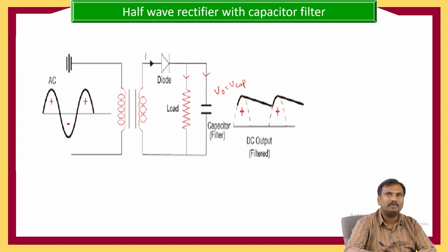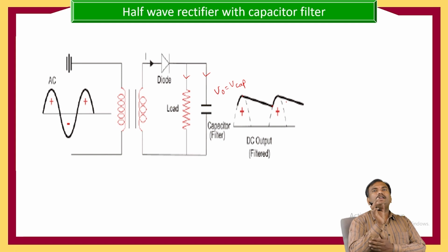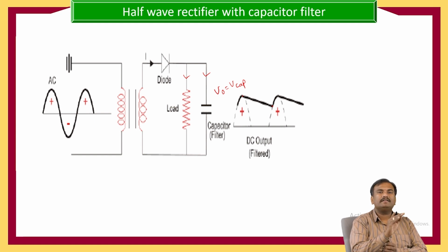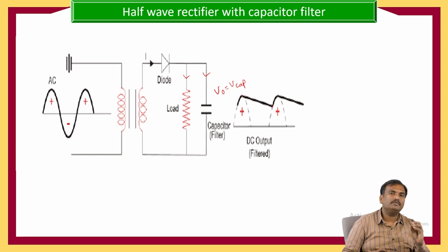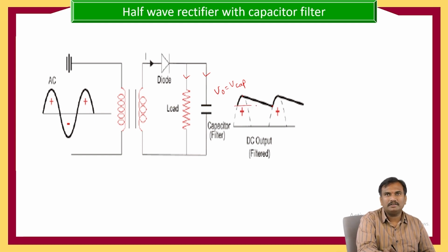Once we reach the next positive half cycle, the capacitor again charges and discharges. In the positive half cycle, for 90 degrees, the capacitor is going to charge, and for the remaining 270 degrees, the capacitor is going to discharge. We choose a capacitor with a high value so it stores the energy needed to produce the complete voltage. With this, the constancy in the output voltage will increase.